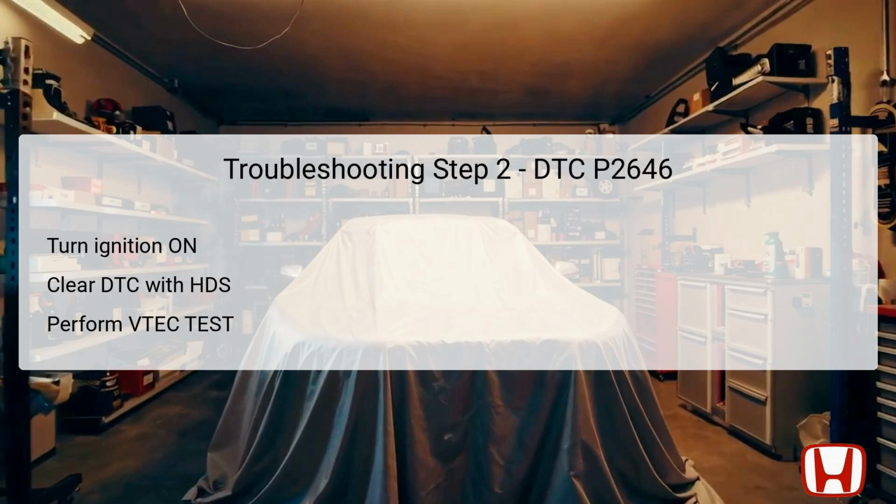If the results indicate that the failure is intermittent, check for poor connections and loose terminals at the rocker arm oil pressure switch and the powertrain control module, or PCM. However, if the failure persists, proceed to the next troubleshooting step for detailed inspections.